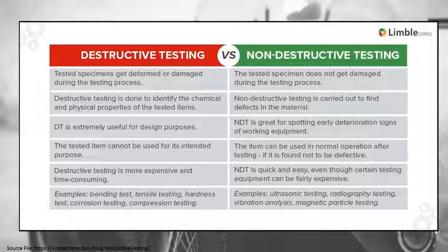Examples of destructive testing are bending test, tensile testing, hardness test, corrosion testing, and compression testing. Examples of non-destructive testing are ultrasonic testing, radiography testing, vibration analysis, and magnetic particle testing.